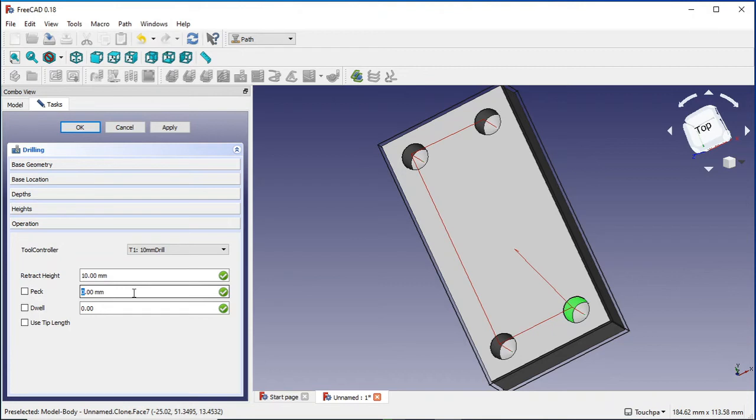So normally I'm going to go on there for 2D, which was 10mm, and that will allow the drill bit to come down and into the stock. You would use this on hard stock that's quite hard to get through, so it just nibbles away at it. Also, if your machine can't handle a straight drill into the piece of material, or the drill bit is of very soft metal, you'll use a peck in there. To define the actual peck millimeters that you would use is all down to trial and error and your machine itself.